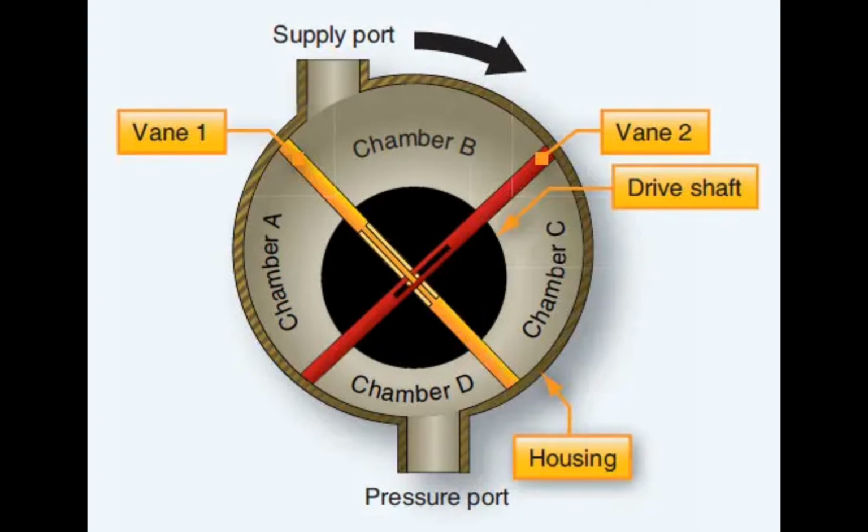Why should a pneumatic system be purged periodically? Remove contamination. Moisture, oil from components, lines. Name the filters used in aircraft pneumatic systems. Paper, pleated, and screen.